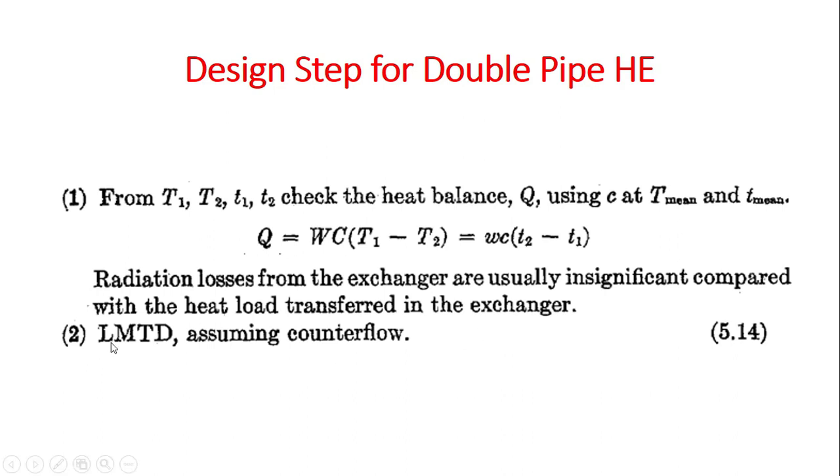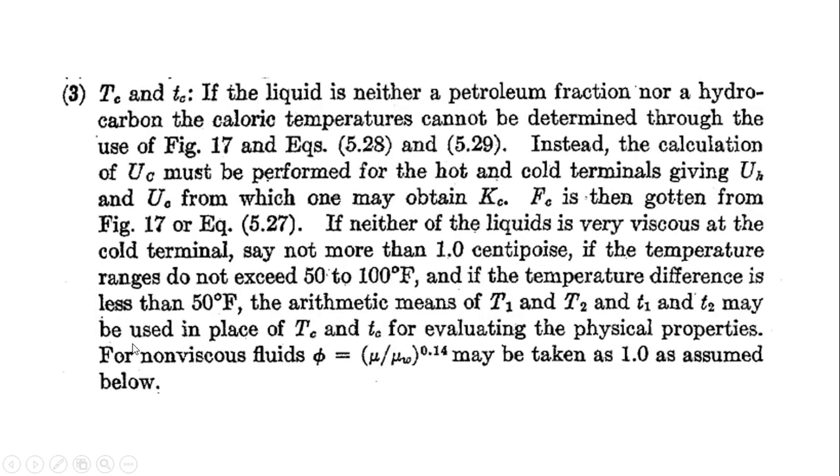the heat exchanger. The second step is to determine the LMTD, log mean temperature difference, using these four temperatures, assuming countercurrent flow, because in the previous lecture we have seen that for countercurrent flow the LMTD would have the higher value.